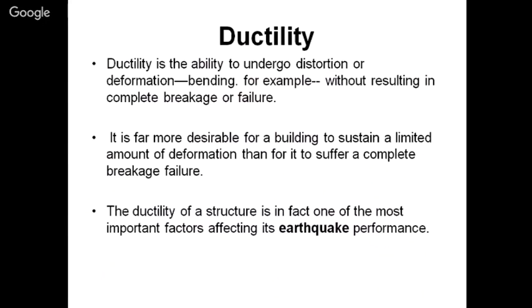It is far more desirable for a building to sustain a limited amount of deformation than for it to suffer complete breakage failure. Ductility of a structure is in fact one of the most important factors affecting its earthquake performance.